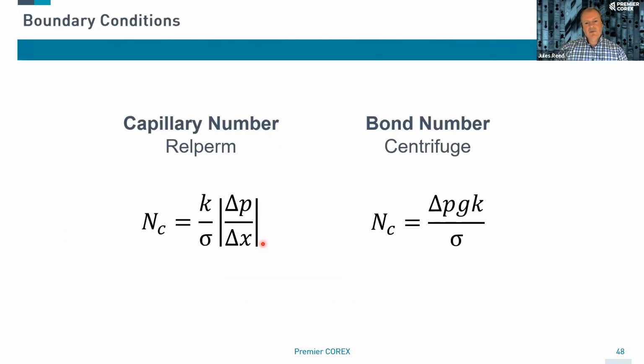And then we need to look at, well, what is currently the best method to determine true residual oil saturation? And I would suggest that at the moment, with the current practices and the current equipment that we have, for most reservoir systems, and this won't be all, but for most systems, the best method will be the centrifuge process. So a centrifuge test down to true residual oil saturation.